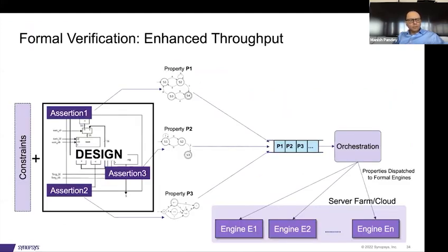Looking at another problem, this is about formal verification. This is an important verification technique where, given a design and given an assertion, rather than use simulation, you analyze the state machines comprehensively through a set of different techniques, and determine whether or not these properties hold true under every condition. Formal verification, as a field, has seen tremendous advances in the last 20 years.